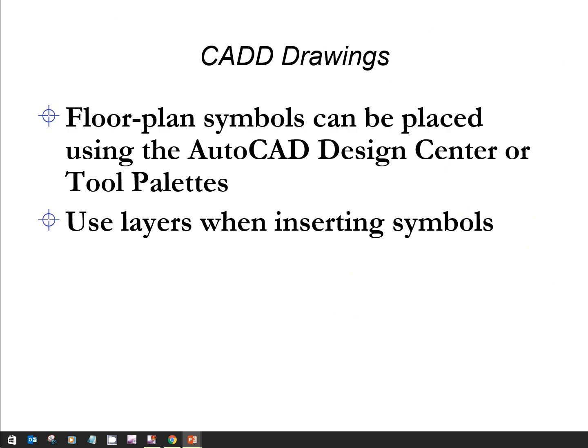And as always before, use your layers when you're inserting these things so that they're on the correct layer. And it's always easier to use the symbols in the design center or a block that's already created.